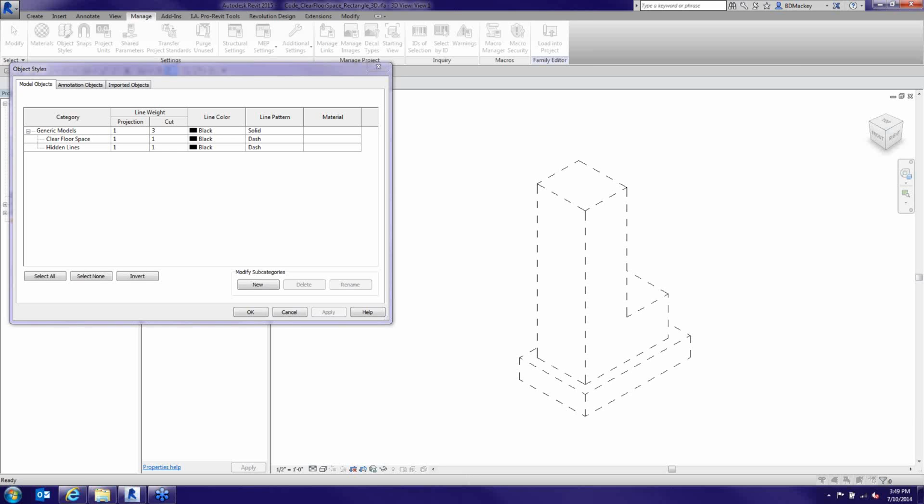I do it with ductwork, I do it with pipe, and in that connector I also can nest a void, so then that void can automatically cut the wall. At every wall where I want to do it, I can put in this connector right at the wall and then cut the wall, and that void that cuts the wall could be used for clearance or interference checking as well.